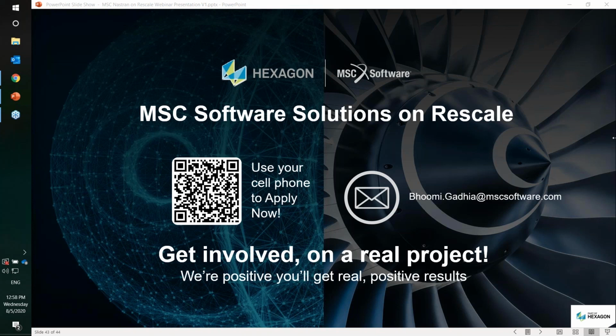There's a follow-up question to that. How can you download results from a DOE run since there may be many? Yeah, sure. So Rescale makes it very convenient with the DOE in that it keeps all of the results contained and associated with that individual job. And so you have several different options. First of all, you can go through and view the results, filter them by, say, file extension or file name, and download files individually.